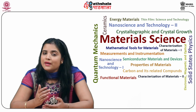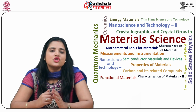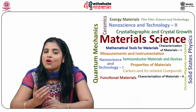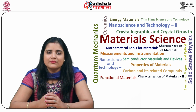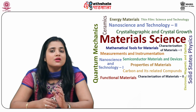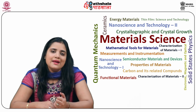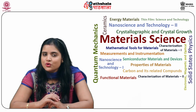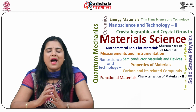This method is based on the use of a number of comparator circuits which are arranged in parallel. Hence, analog to digital converter based on this method is also called a parallel ADC. In general, for n-bit digital output, the number of comparators required is equal to 2 raised to power n minus 1.